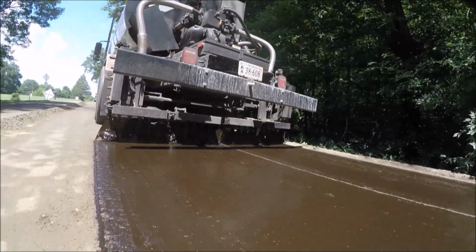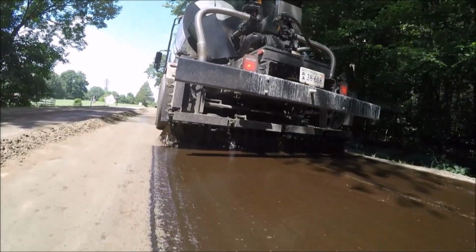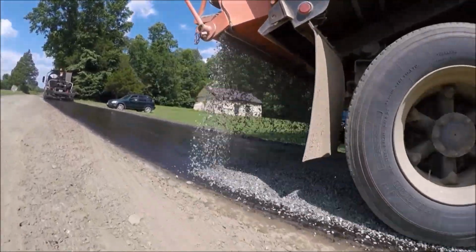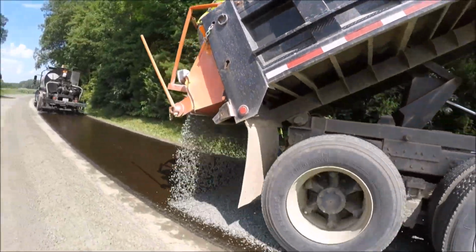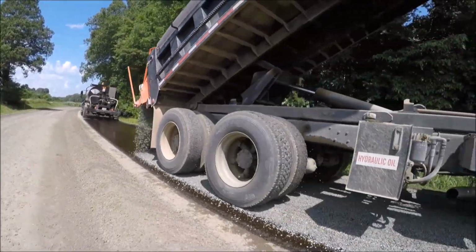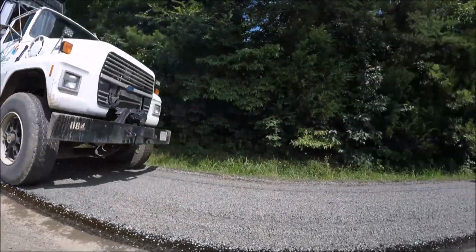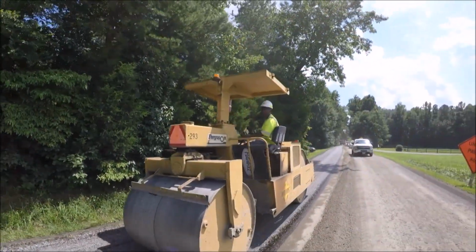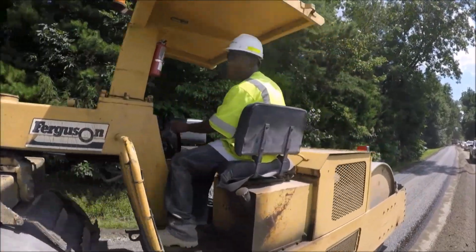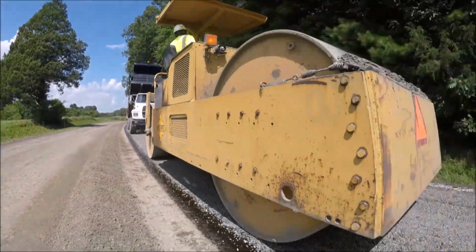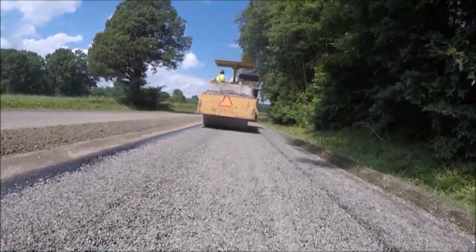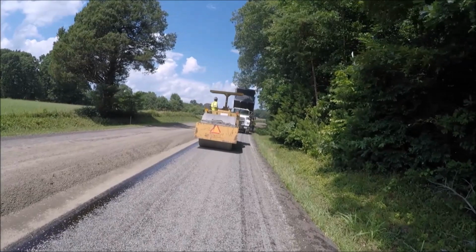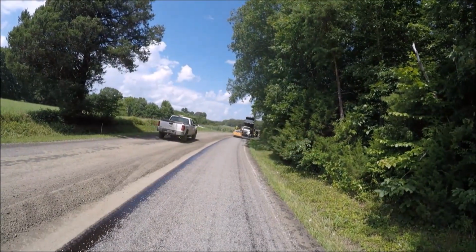In a lot of cases, in this particular case, VDOT employs chip seal not as a final surface, but as a temporary surface for the traveling public. So it serves two purposes. One, it seals up that material and allows the material to hydrate below. It also gives the traveling public something to ride on until it receives 2 or 3 inches of asphalt. You can see here the northbound lane is now almost complete. Once they've completed that section, they will immediately turn traffic onto that section and work on the other side.